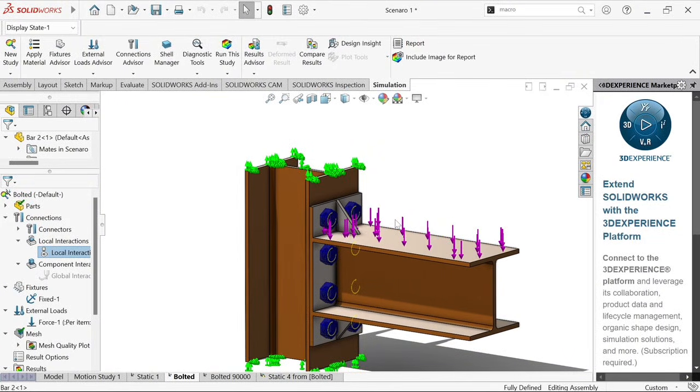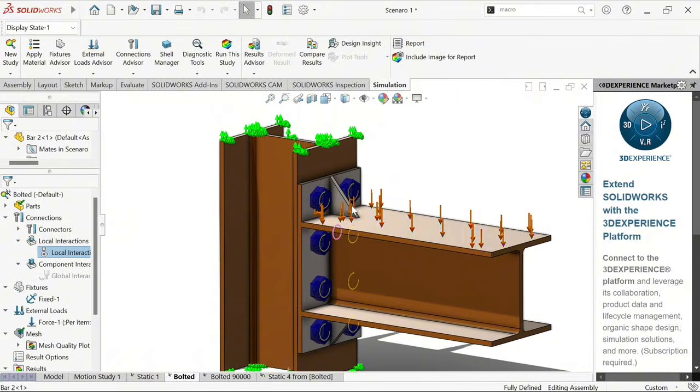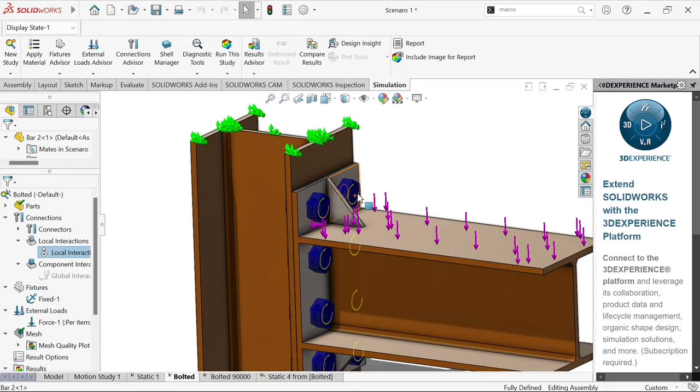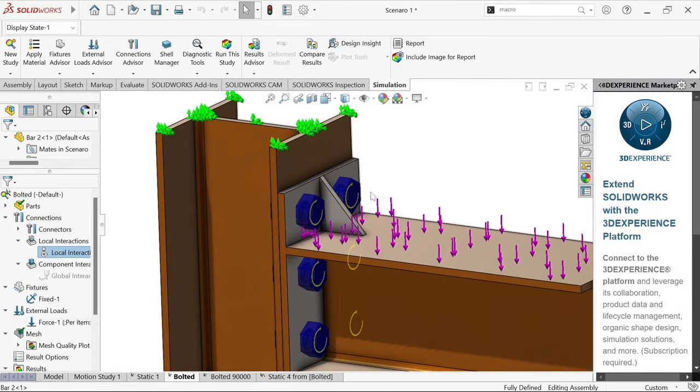Then we make a very, very important input here. This is because for the bolts themselves, I didn't use physical bolts, because the physical bolts would increase the mesh time, and we would not get what we actually want. The physical bolt would act just like a placeholder. It wouldn't mimic anything, it would just be there passive and make the design complex. We want the bolts to be present, but not just present. We want the bolts to actually function.